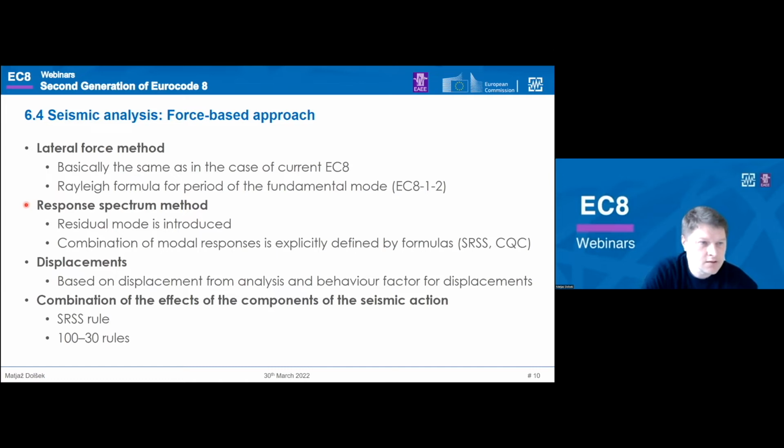Then regarding the response spectrum method, again it's the same. The residual mode is introduced. This is new. You know that in the response spectrum method, the question arises how many modes you should take into account.